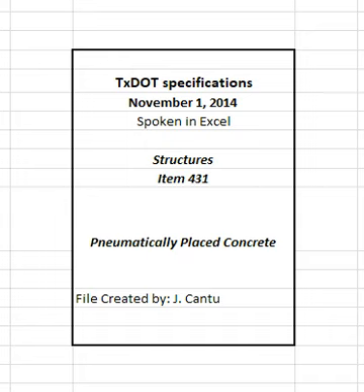3.2 Surface preparation. Grade the area of proposed work accurately to the elevation and dimensions shown on the plans when concrete is to be placed against soil. Compact with sufficient moisture to provide a firm foundation and to prevent absorption of water from the concrete but without free surface moisture. Remove paint, rust, loose mill scale, grease or oil, and all other foreign materials that may reduce the bond of the concrete to the steel when concrete is used to encase structural steel members.